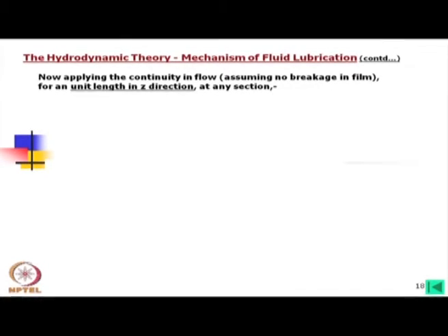You will find that for continuity in the fluid flow, or for the film not to break, we have to satisfy some conditions. That will come automatically and we will see whether it is being satisfied. But there are also some external reasons: a film may break even while satisfying all hydrodynamic conditions. Suppose there is a particle inside the fluid that has somehow entered, or a roughness has developed on a surface; that also may cause the breakage. But let us consider that there is no breakage and no particle inside the film.